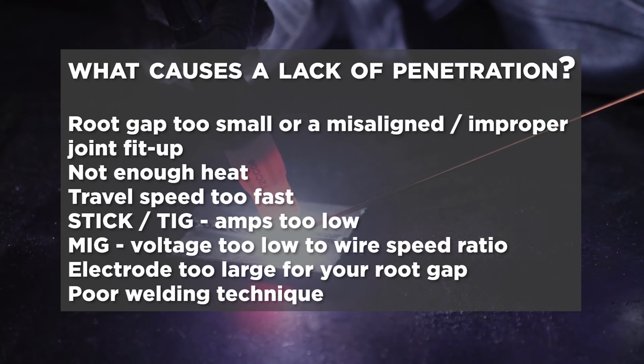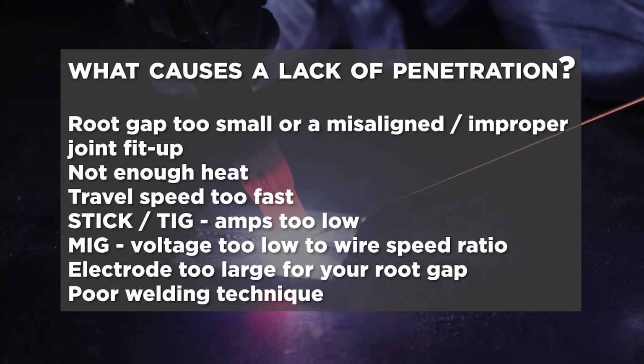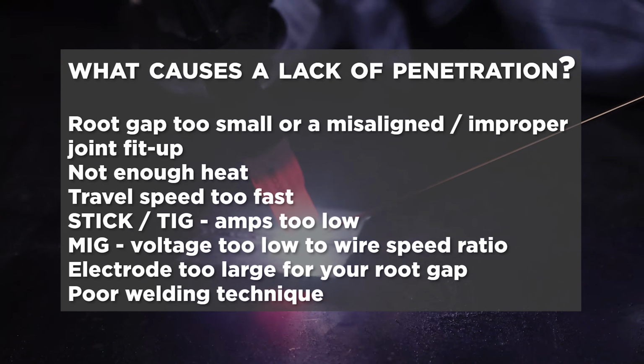So what causes it? Too small a root gap or a misaligned, improper joint fit up. Not enough heat, travel speed too fast. For stick and TIG, your amps could be too low.